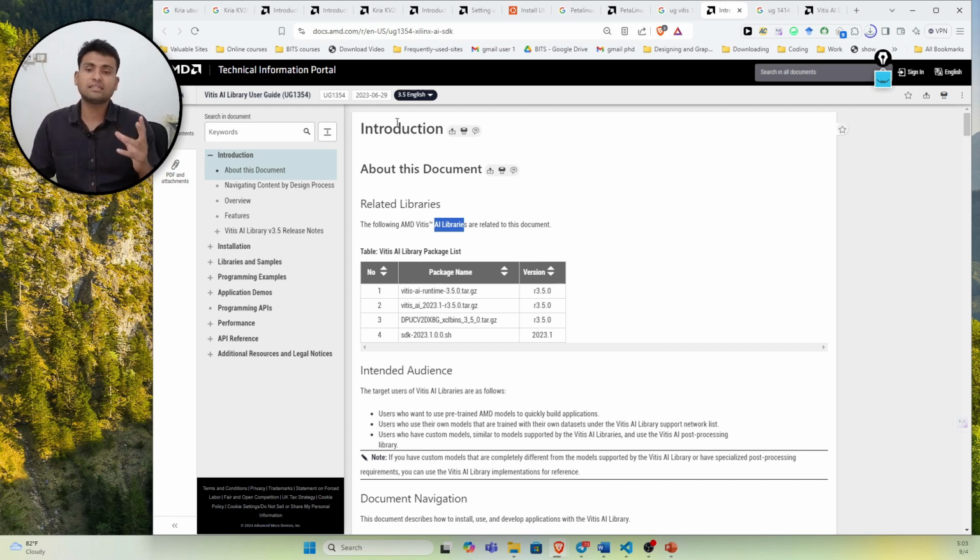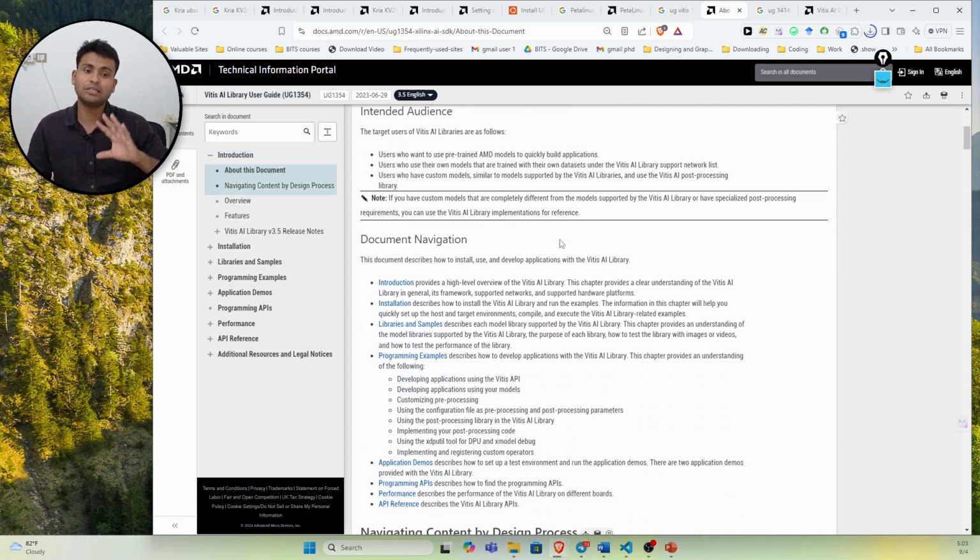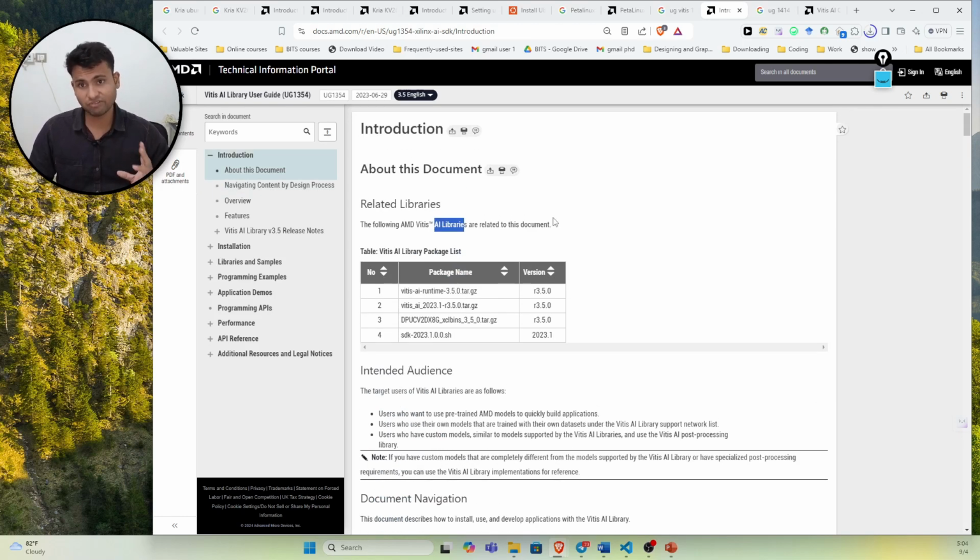On the other hand, with Petalinux, you can deploy something known as a deep learning processing unit on the PL part of your FPGA. More of this will be clear if you see the theory video lectures on what exactly a deep learning processing unit is. So we have a DPU running on our FPGA, which we can utilize. One way to do that is to install Vivado and Vitis, create a deep learning processing unit, and interface it with everything. But Xilinx has already done all that and created an image which we can directly burn and download at our end.